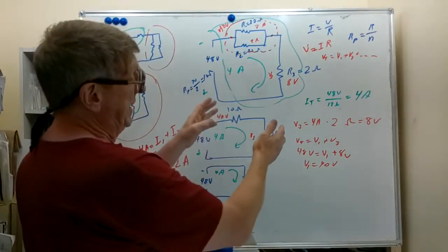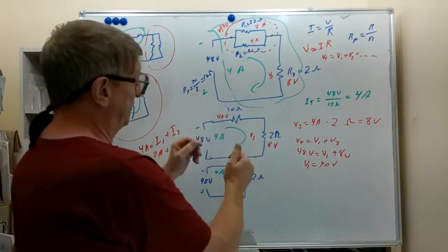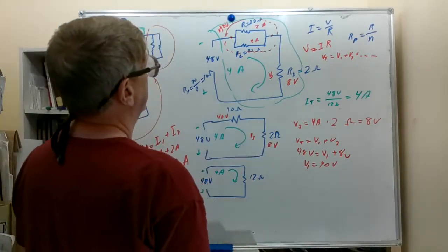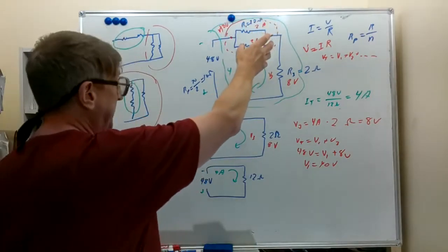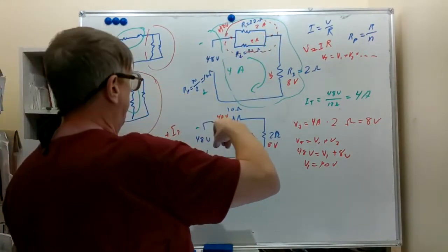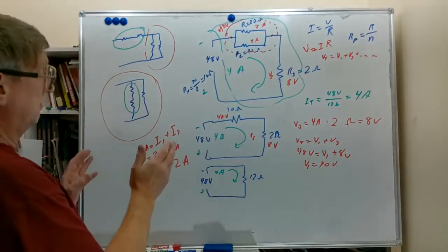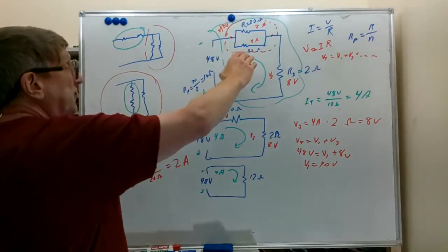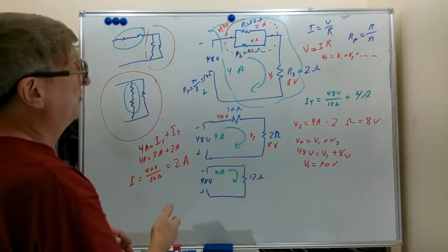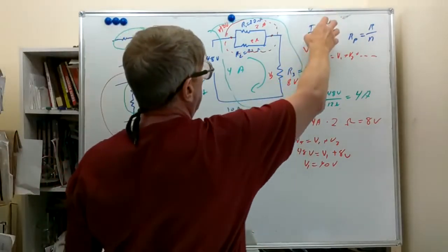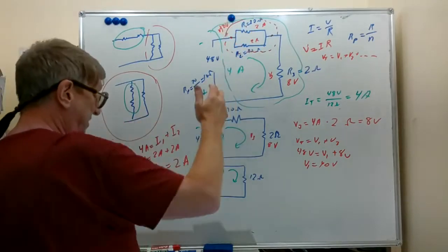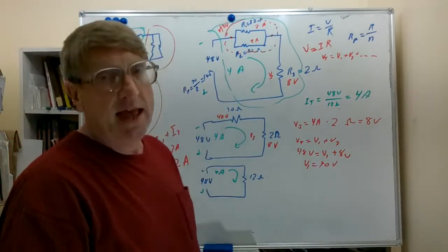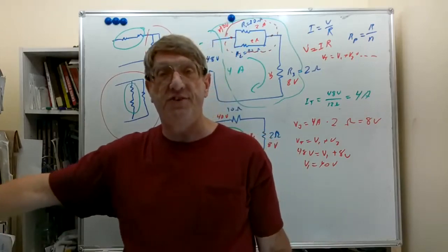Then we worked our way back using voltage drops, or what we often call IR drops. And then we used a current divider formula here because they were equal. And we also solved the branch currents by using this formula and the voltage we found when we calculated voltage drops and the given resistances. Anyway, I think we'll call that good for today.